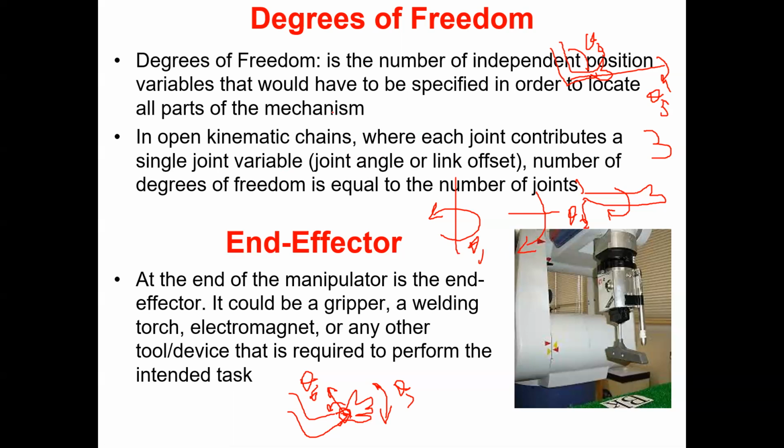Okay, so there are redundant manipulators with more than 6 degrees of freedom, like 7 degree of freedom manipulators or 10 degree of freedom manipulators. When you have more joints, the manipulator becomes like a snake, so it can change the configuration quite a lot in order to exercise various movements.